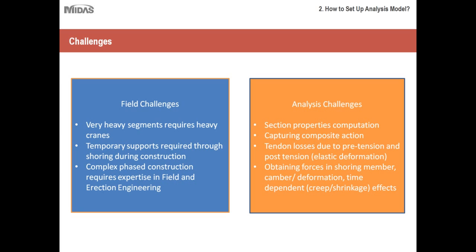Again, this one section is constructed in 3 different steps, and there will be a time where the girder will be by itself, then there will be the girder and the lid on top, which will behave as one section, and then after some time there will be a third part added to this section. So you have to capture the behavior of the entire cross section in different stages.